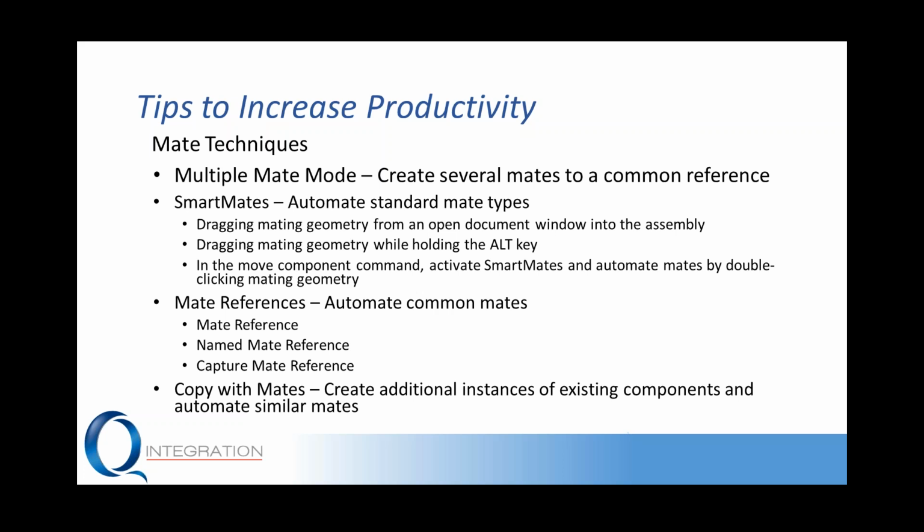And then we'll take a look at mate references. Right, so when we're inserting these components, it might be kind of nice to have it just snap into place, maybe concentric to a hole or coincident to a flat face. And we can do this by utilizing mate references. And we have a few different types of mate references. We have a standard, just regular mate reference. We also have named mate references. And we can also capture a mate reference.